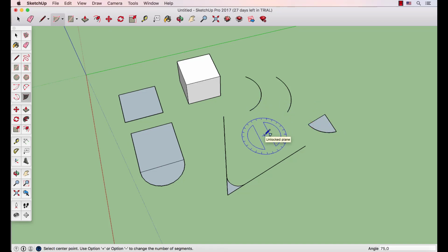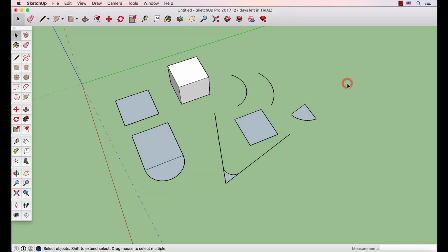Besides the lines and the arcs, with which we can create any shape, SketchUp provides us with some tools that help us form basic shapes such as rectangles, circles and polygons. In order to draw a rectangle, we select the Rectangle tool from the toolbar. Then we click on the point where we want to place the first corner of our rectangle, and we pull the mouse towards the preferred direction, where we click again in order to complete the rectangle. We can draw rectangles at any point and with any orientation, on any existing shapes or objects, or start from an edge of our model.